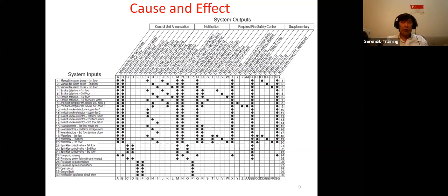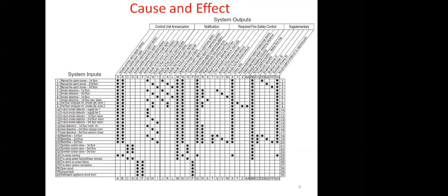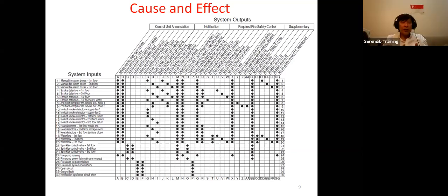But what I said is, if you're going to have two detectors, what is the purpose? The purpose is redundancy, which means if the first detector activates, is it a fire? No. If it's not a fire, you should not evacuate the building. Let the second detector be activated. Then it's a confirmed fire. Everybody agrees. Then that's where the discharge will start. The counting of the clean agent discharge will happen, and evacuation can take place.